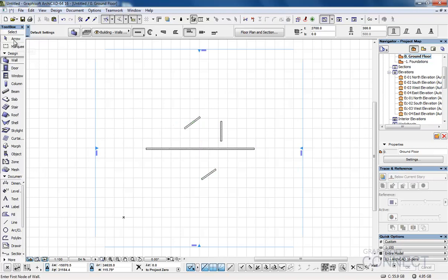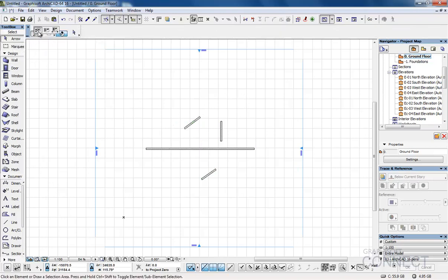And this is controlled by the arrow tool and this very first box in the info box. As long as it's set for the third option, which is not always the case by default, so you may have to check that. As long as it's set for this third one, you then get direction dependent selection. So in this case, left to right gives a centre line. If I go right to left, a dotted line. And what I want to do is pick everything up and just delete it.